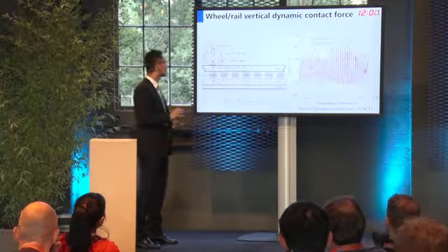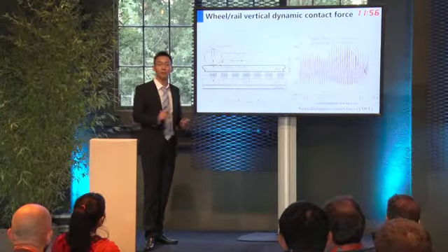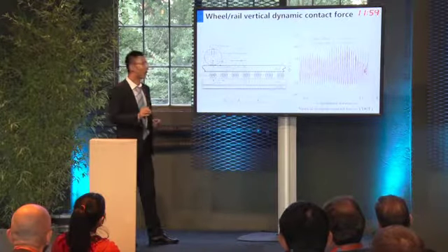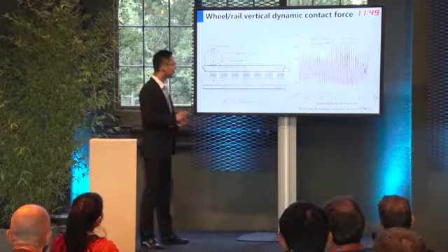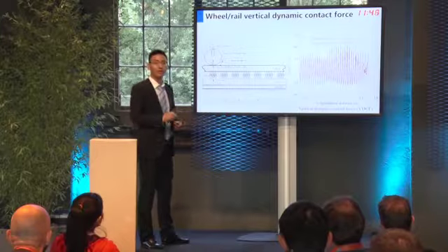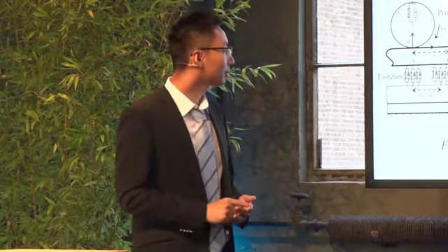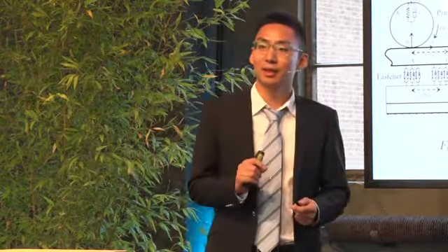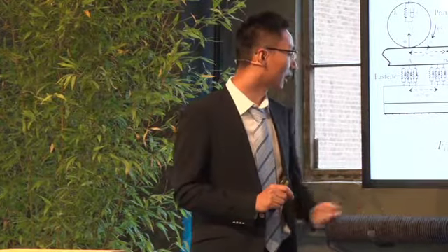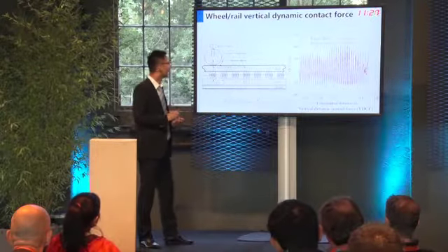By using the transient rolling contact model, we study the influence of the resilient wheel by comparing it with the rigid wheel. Firstly, we give the vertical dynamic contact force, which is a significant consequence of the wheel-rail interaction. The dynamic forces are calculated by subtracting the force on the smooth rail from the force under the corrugation excitation.